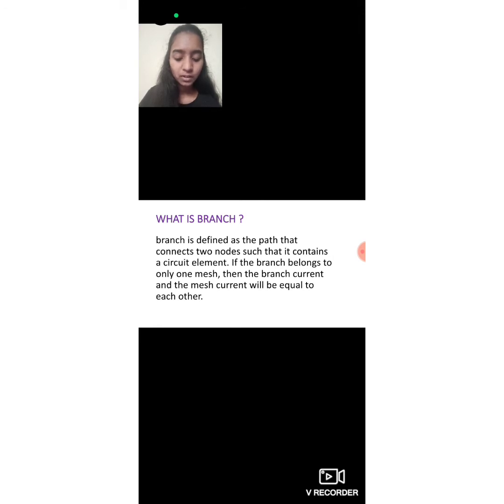A useful reference node is one which has the largest number of elements connected to it. A useful reference node is one which is connected to the maximum number of voltage sources. Place all sources on the right hand side of the equation as inhomogeneous drive terms. The terms comprising each element on the diagonal of matrix A must have the same sign. If you arrange so that all diagonal elements are positive, then the off diagonal elements are negative and the matrix is symmetric.